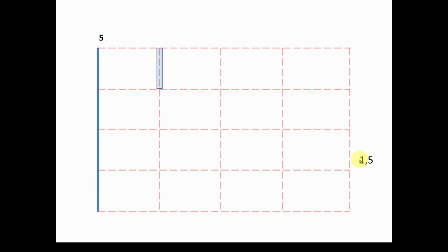And then we want to place the first bus that has a line going to it from this bus number 5. So let's say we've got a line to bus 1 from 5, and we need to place bus 1. Well, as you can see, all of these positions are available to place bus number 1. But how do we go about figuring it out? Well, what we can do is for each occupied position for bus 5, we can step one column to the right and say, hey, is this available? And in this case, there's no bus here, so this is available.